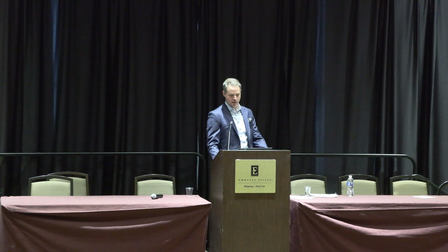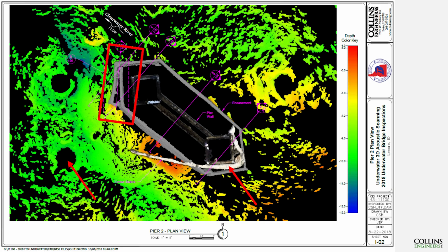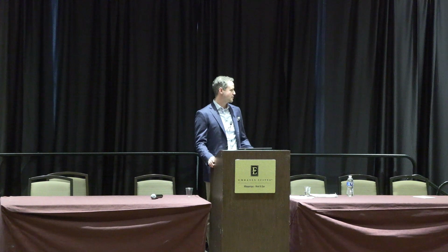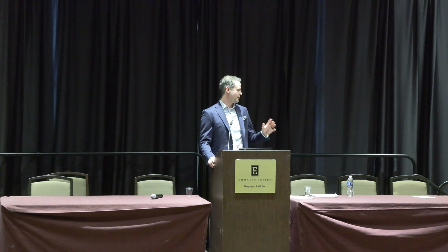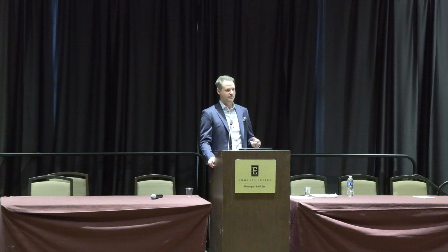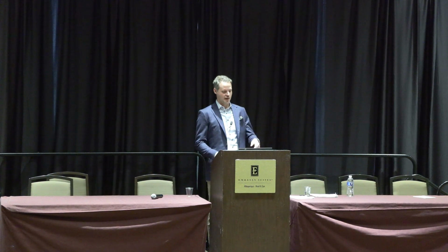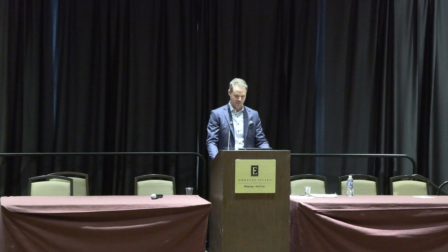So this is the same pier, but now we're looking straight down in a plan view. You can see the tree again. Upstream is on the lower right side of the screen. The black circles right there are actually where we did the individual sonar drops. So we had to physically drop it all around each pier to get a full scan around each one. We had to tie up the boat, throw it in the water, get it in position, do a spherical scan, check the data, pick it back up on the boat, move, drop another one, and you can see how we did it all around the pier.